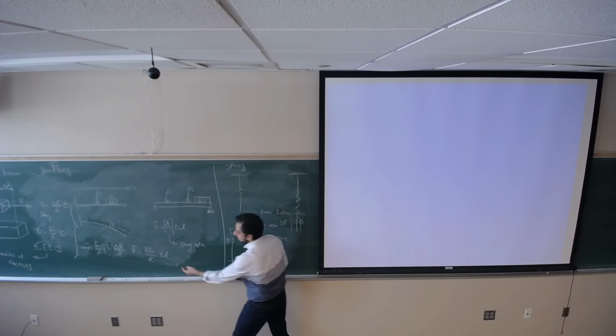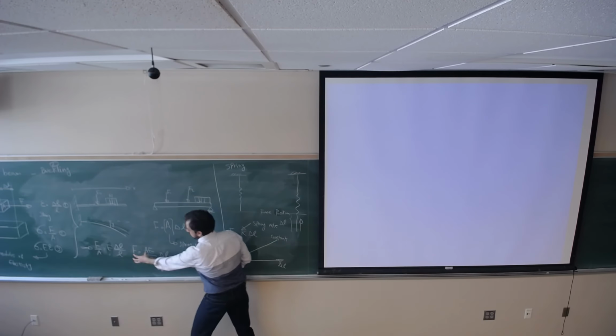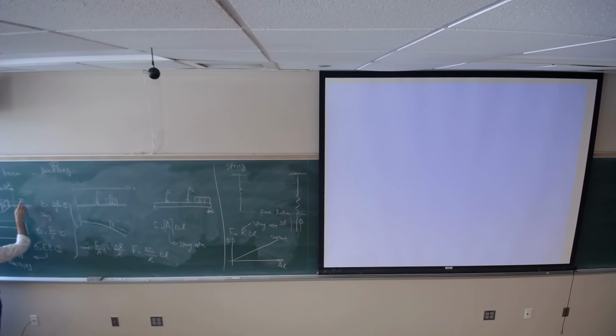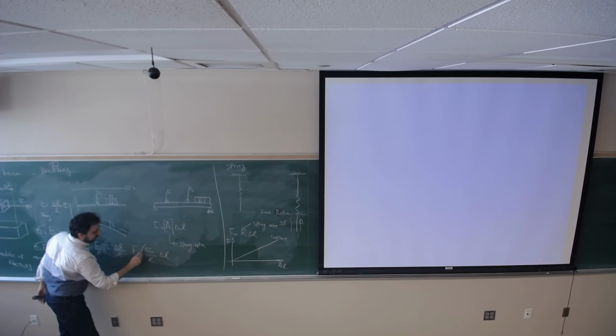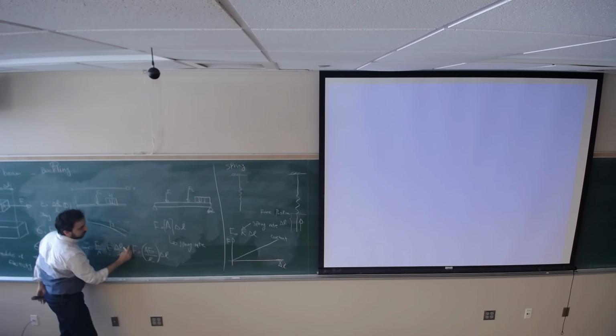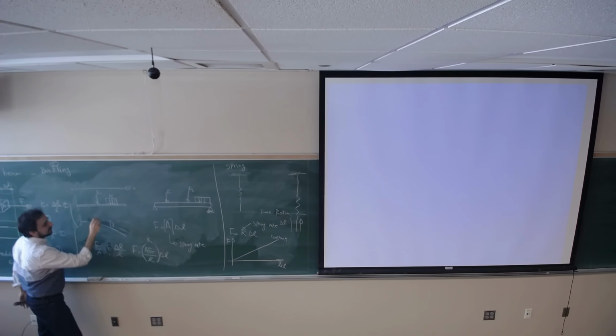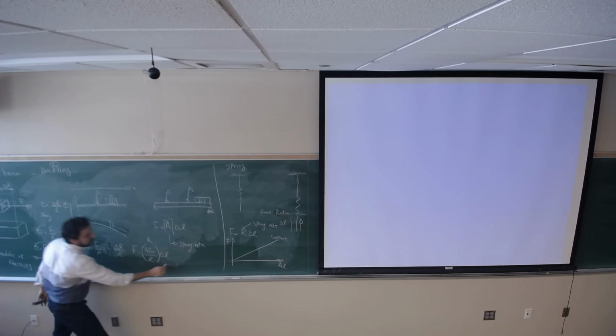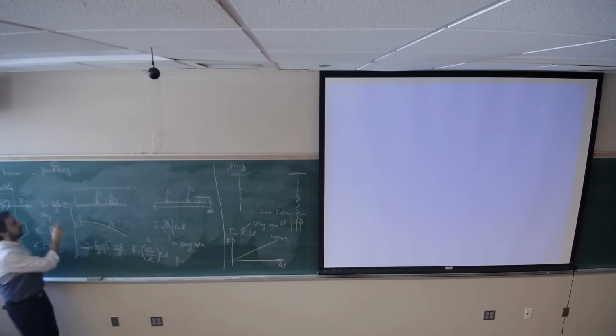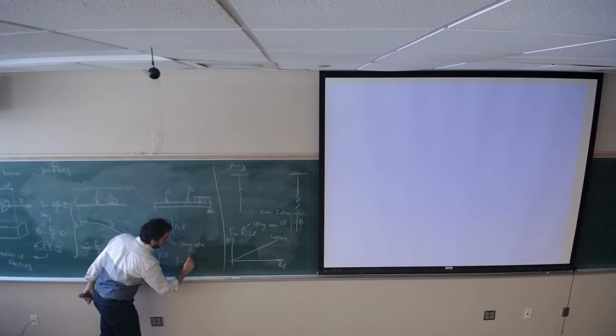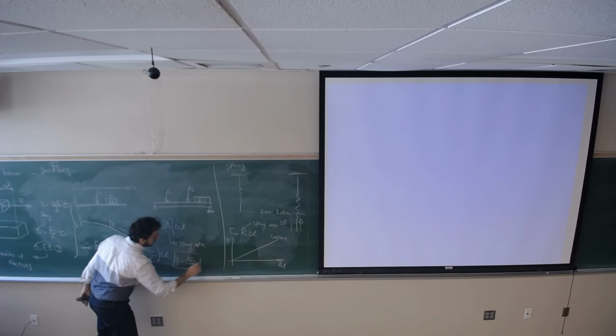So now this equation is gonna show me the relation, the correlation between the force that we apply and the elongation that we get. So if you compare, this coefficient connects force to elongation. So the stiffness or spring constant for a rigid bar, which is under axial loading, is gonna look like AE divided by L.